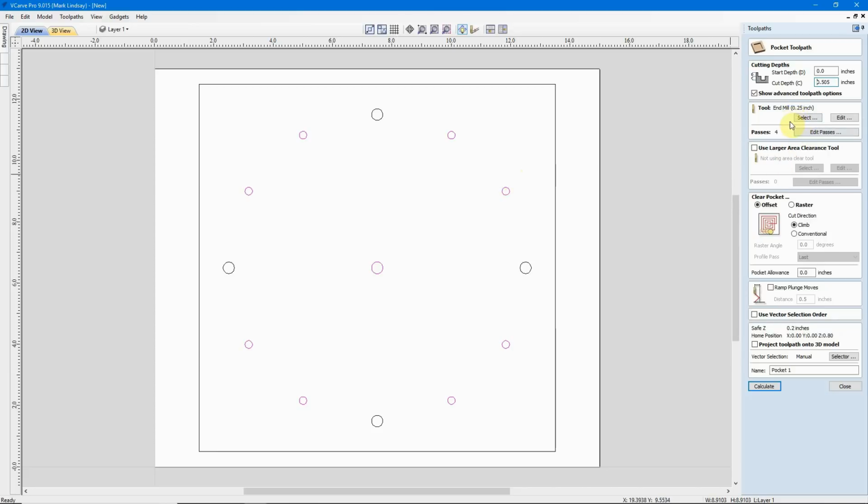I have got to remember to use an upcut bit when I machine this hole. An upcut end mill will eject the chips and sawdust upwards out of that hole. A downcut bit will try to force them down into the hole that I'm trying to cut. That will create friction, and that friction will start burning. It will get that hot.